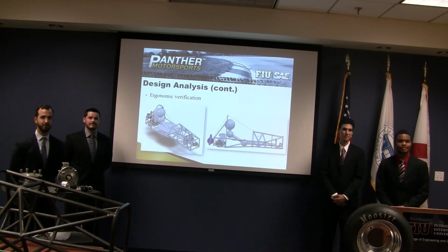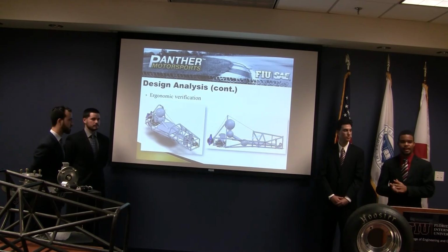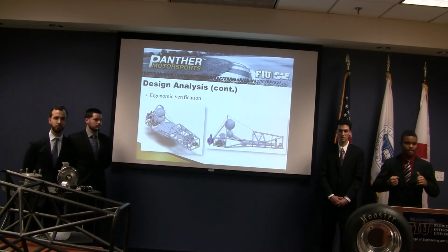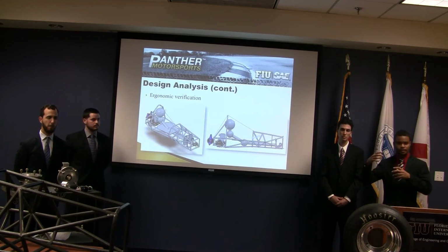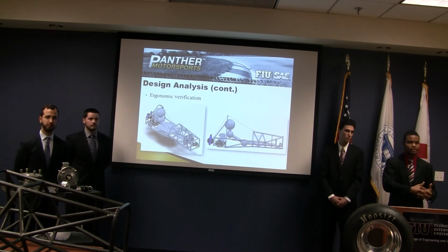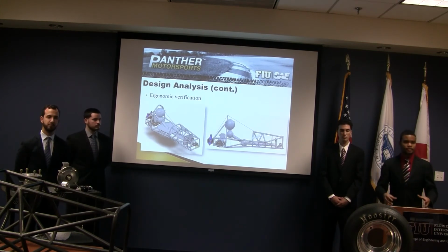Any other questions? I have a question. What type of analysis did you do that was different from the last one? I know you made a different design, but what was different in the analysis from one year to the next? Well, last year there wasn't exactly a comprehensive analysis of the tire data, which is really important because the basis of the suspension is to maximize the tires. By analyzing the tire, we can see exactly what the tire can do, and we can optimize the suspension and therefore reduce the chassis weight, because we were able to work all these different systems in parallel and put them together to improve the overall performance of the vehicle as a whole.